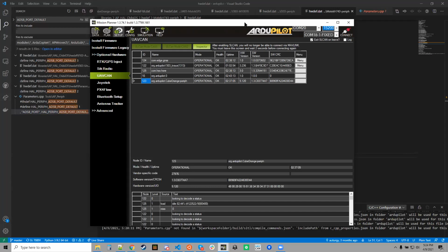Right. And I think for firmware update, basically we need to implement the bootloader client inside ArduPilot. There's an API within UAVCAN for doing file transfer, and we need to implement the file transfer to be able to put the node into the bootloader and transfer a new firmware.